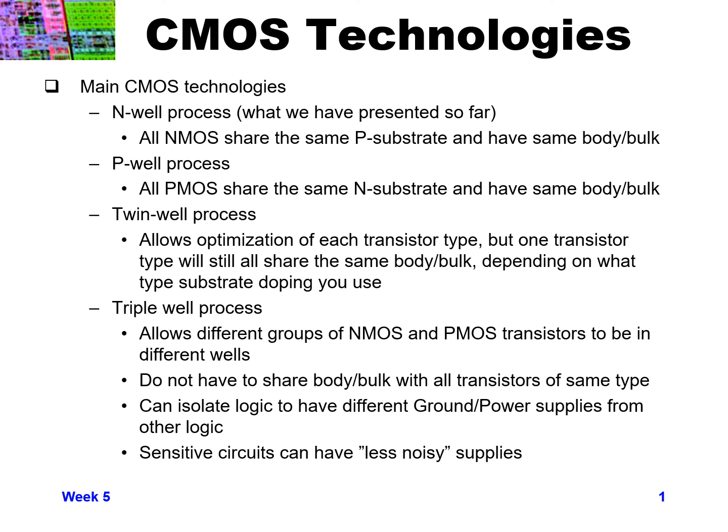So they have certain characteristics based on that P substrate that are all the same. As opposed to in the N-well itself, we have a certain doping for the N-well, and our PMOS devices are in that N-well, and the characteristics of the PMOS devices are going to be determined in part by the doping